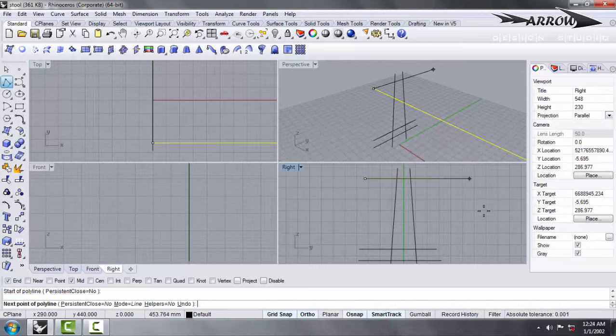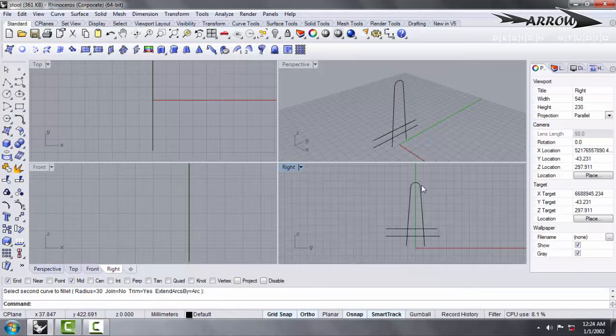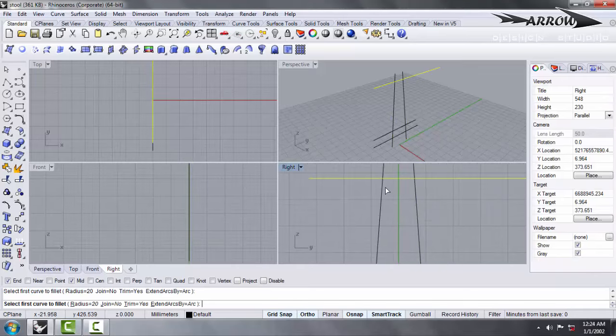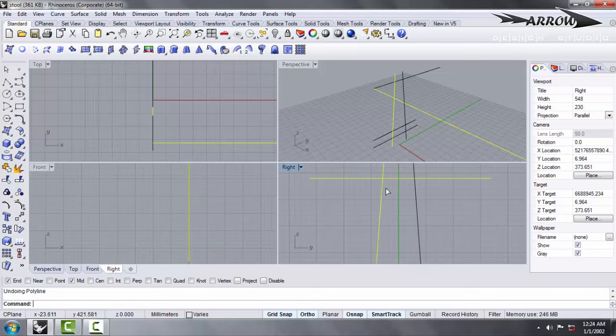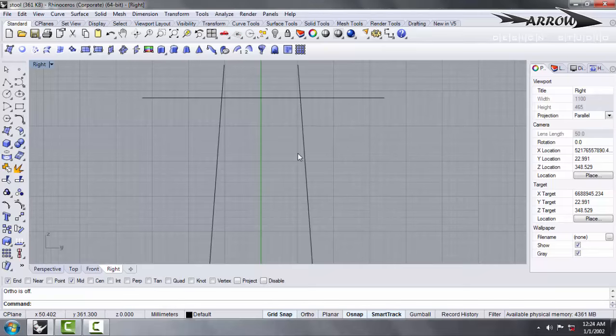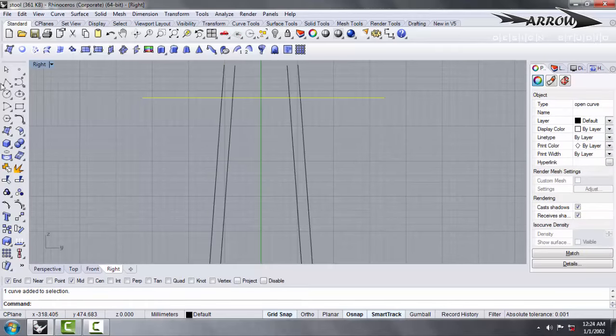But I also need to project these lines over here because these lines are not on that plane. So what I'll be doing is I'll make it fillet now this way, 30, 30. Okay, let us reduce the radius, no issues, because I guess the size has been. So one more thing you need to do is, okay, this longitudinal size I need to just make it offset by 15, not more than that.